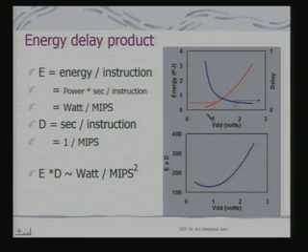Now, these are the typical curves. What you find here is that if I look at the energy, VDD or VCC is the supply voltage. Now, if the supply voltage increases, obviously your energy increases in terms of your picojoule. And if you look at the delay, interestingly, delay reduces. In fact, this is a phenomenon, and we shall look at it in the context of CMOS, what exactly the relations are that have been suggested.